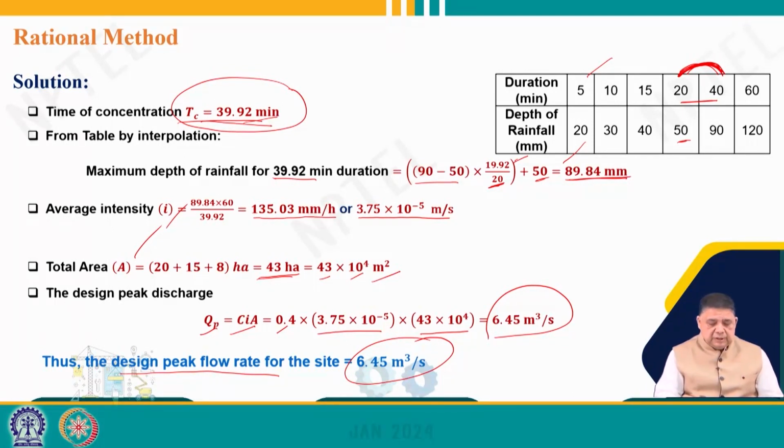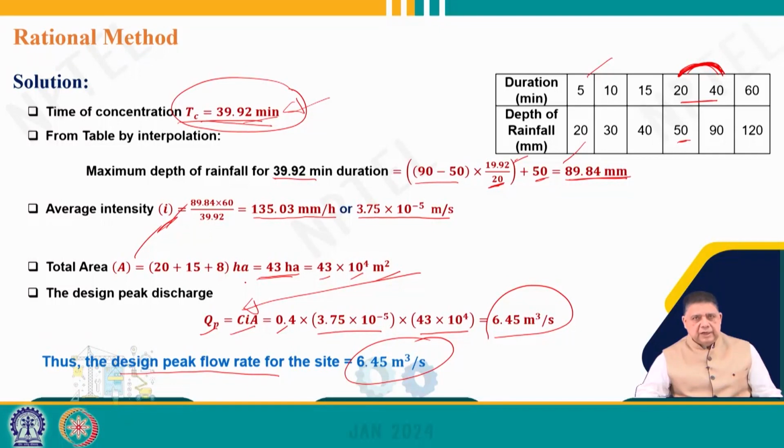Knowing the rainfall for that duration, we have to find the rainfall intensity for the required return period, for which we may have to use the intensity duration frequency curve. And for finding the runoff coefficient C, we have to use the tables already available for different given conditions. So, after knowing C, I and A, we can use this relationship to get the peak runoff rate.